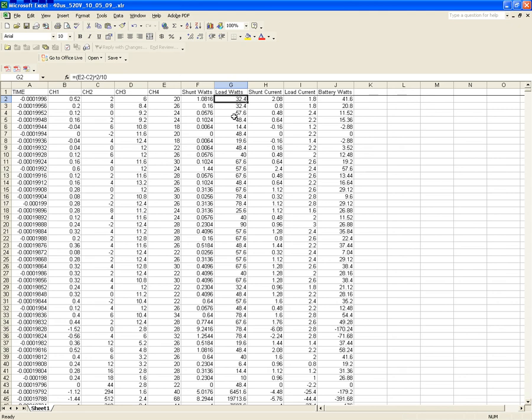The only real way to know is to get the temperature readings, and that's why the temperature is so important in this process, because then we don't have to concern ourselves with that phase shift or how much of a phase shift there is because of the capacitance involved, which negates the inductive phase shift, and they cancel each other out and all that stuff. And so trying to figure out how much current is present at that instant in time. So your load watts here is just a general reference, just to get a feel for what's happening if it was truly an ohmic situation.